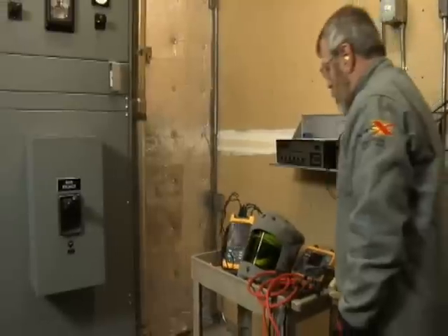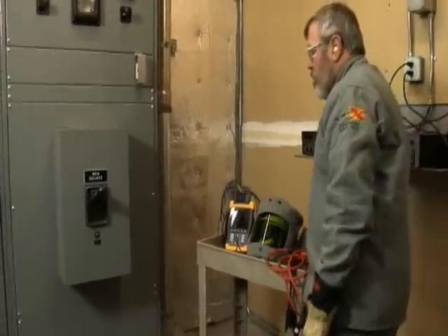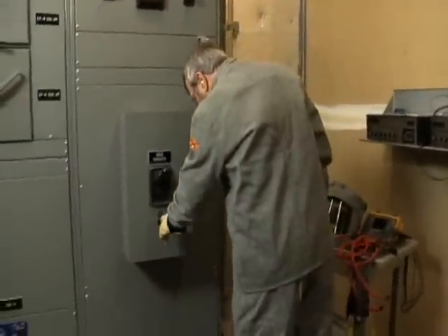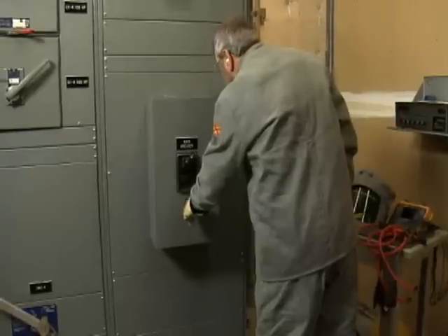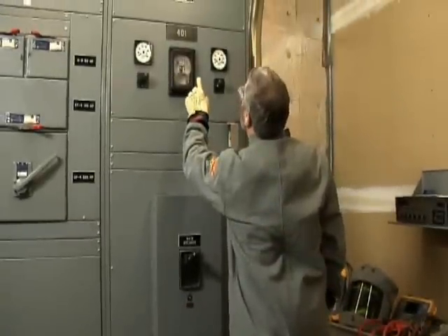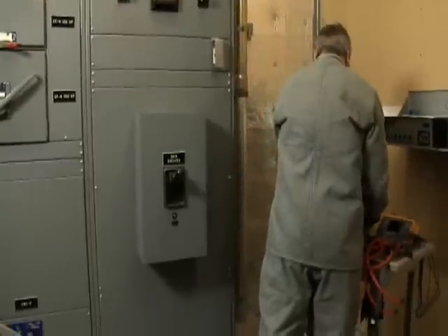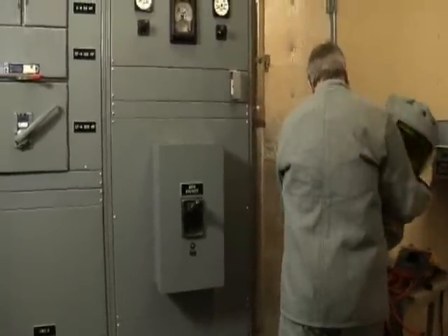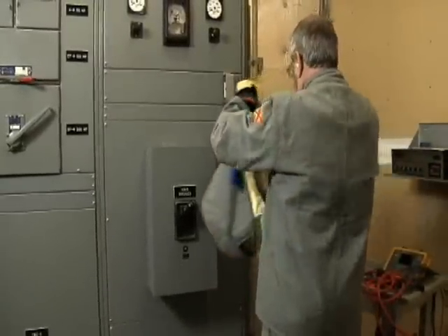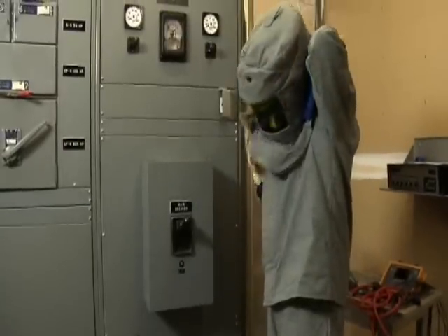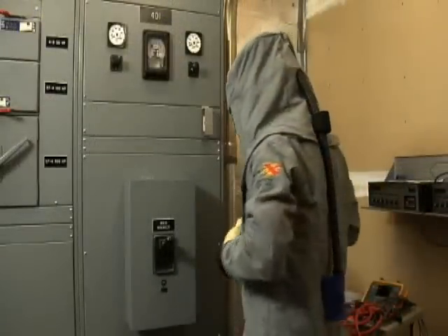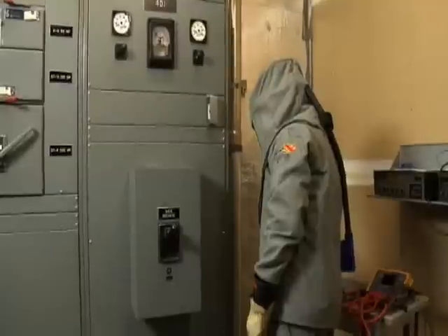Now, let's talk about where to log. I recommend using a one-line diagram to visualize your plant distribution system. Your job is to find the loads drawing the most power. Log power at or close to the service entrance at a safe location. Always make sure of the nominal system voltage before going into a panel. Always select your PPE for the job based on the warning labels on the equipment. If the labels are not present, use the tables in NFPA 70E to determine the appropriate hazard risk category and the required protective equipment.